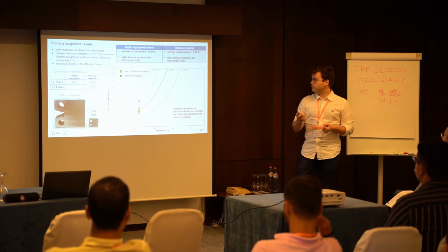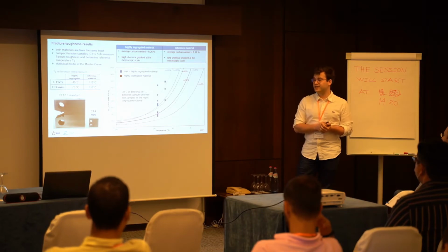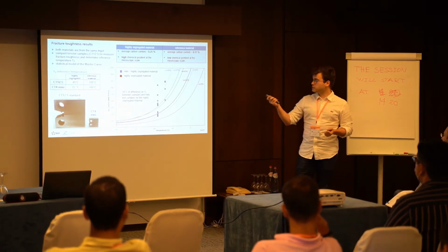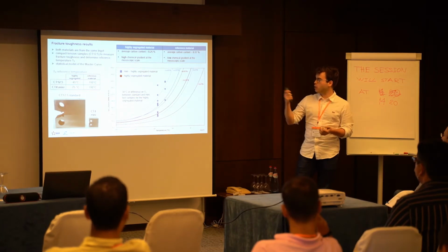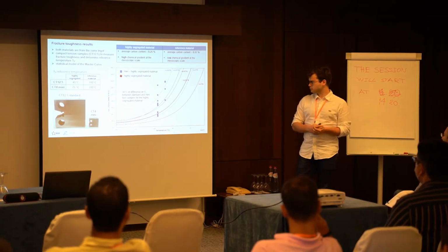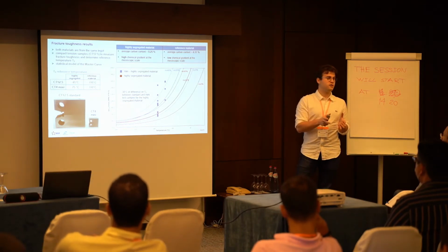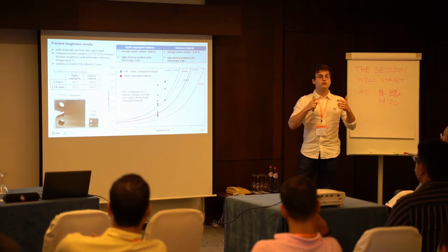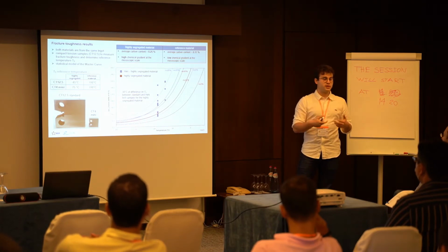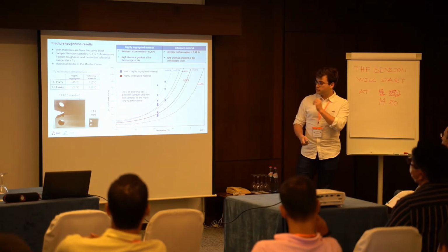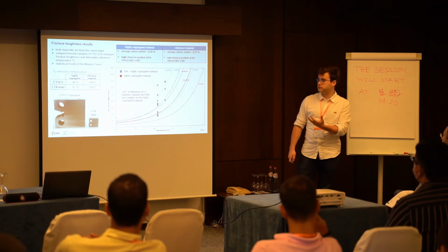However, for the highly segregated material that is much more heterogeneous, there is a 30-degree difference between both reference temperatures. Why? Because when you reduce the thickness of the sample, you increase the sampling effect because of the strong heterogeneity in the material. So that shows that meso-segregations do have an impact on fracture toughness properties.